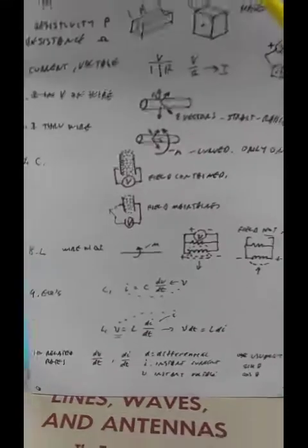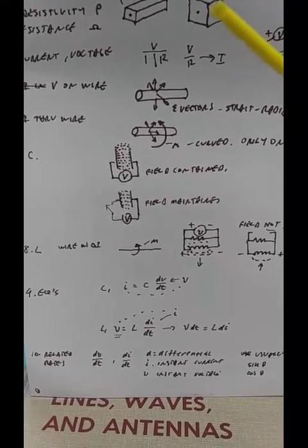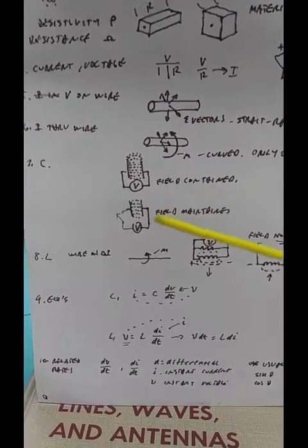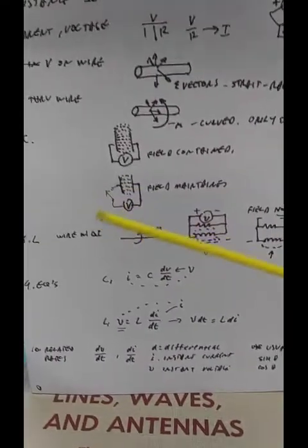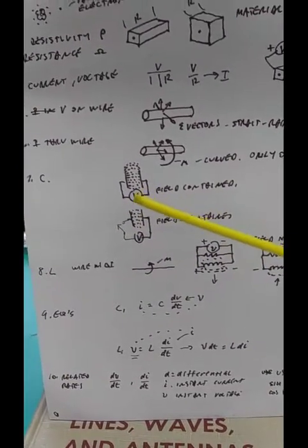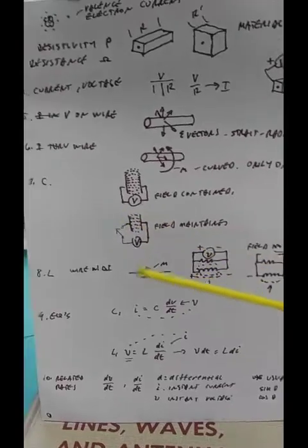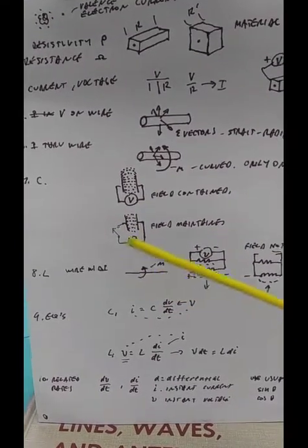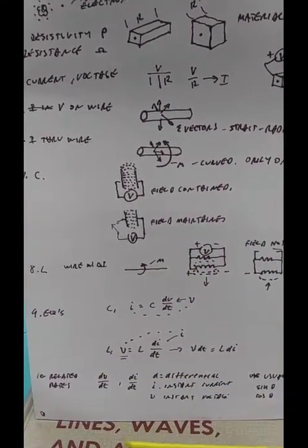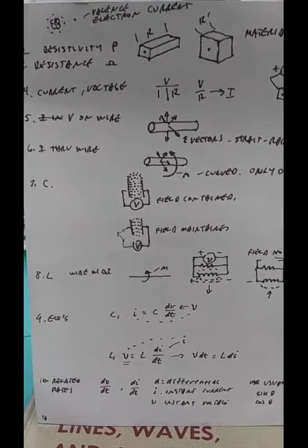They can be taken out of context. A transmission line at 5 kilohertz is a capacitor. I've measured that with an LCR meter. I measured 135 feet of LMR 400-75 from my ham shack out to my 40-meter dipole with, I think it's a 5 kc LCR meter. It read capacitance. I went out and hung an additional capacitance on the end. It read it.